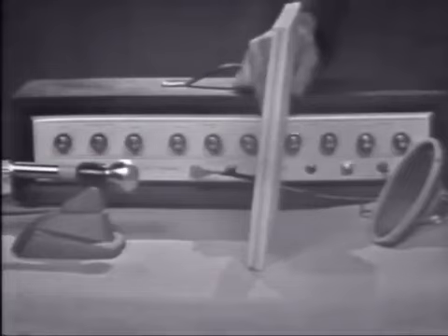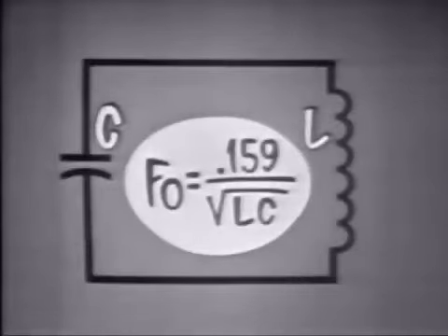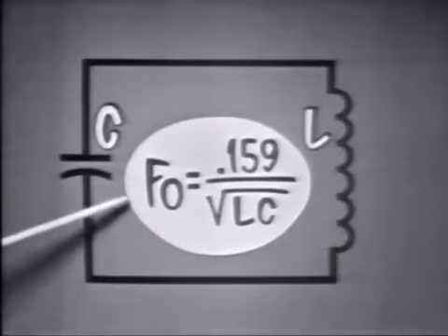We have seen that an amplifier will oscillate without a frequency determining device. But the frequency is determined by distributed L and C, which makes frequency difficult to calculate and erratic. This kind of oscillation is usually undesirable. A frequency determining device, in this case the LC tank, provides a stable, easily calculated frequency.